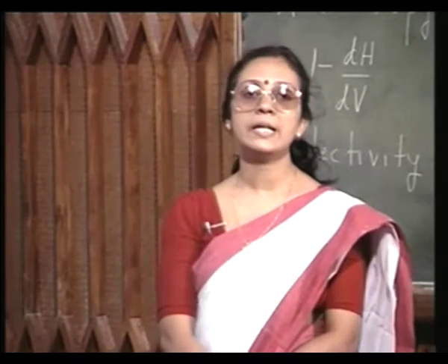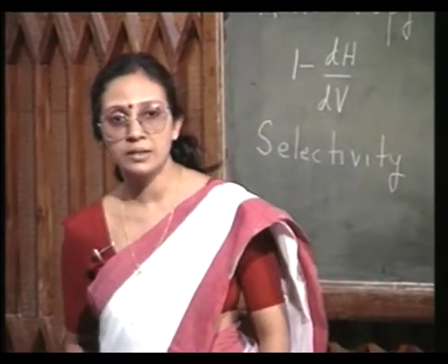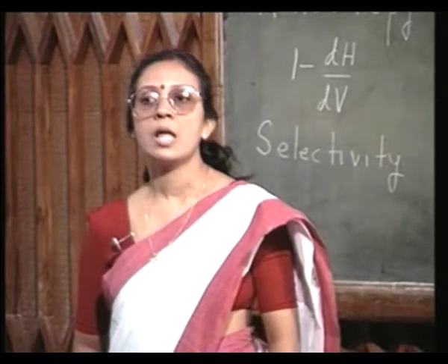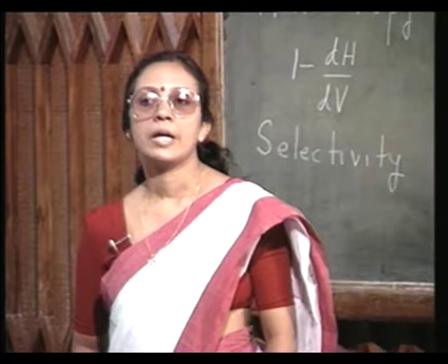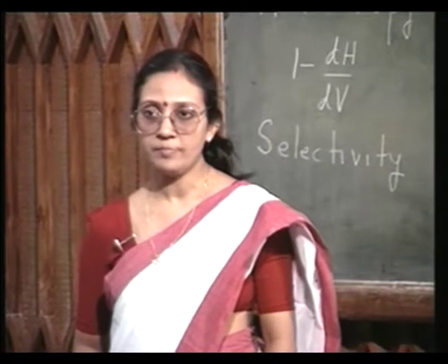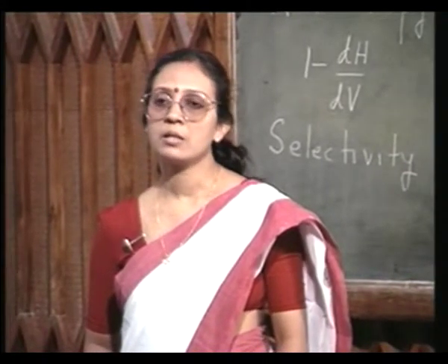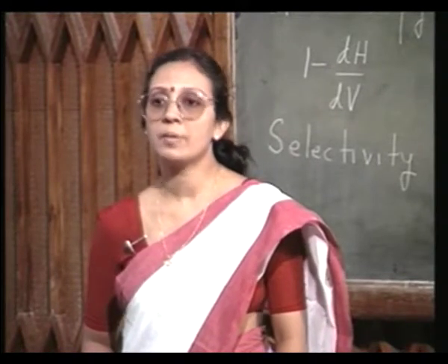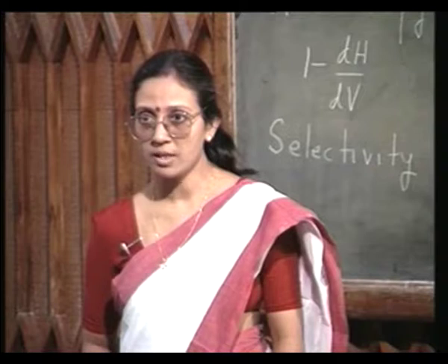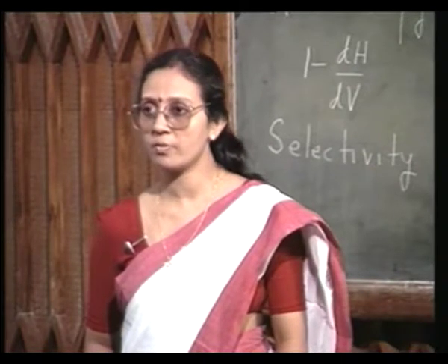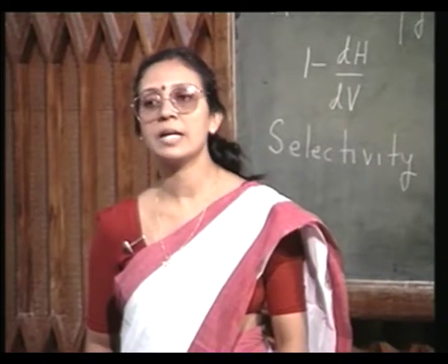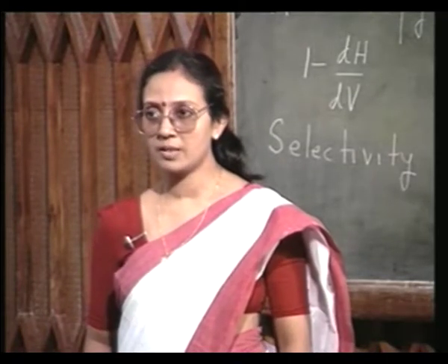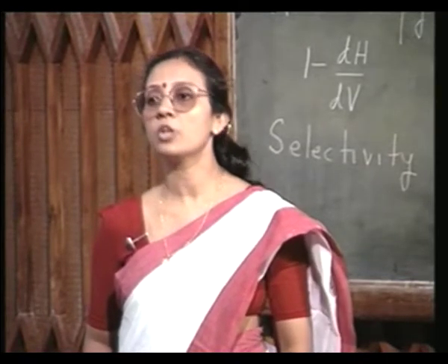So, for any etching system, these are the two figures of merit, anisotropy and selectivity, and any chemical etching system for that matter will have quite good selectivity, because some chemical reaction is taking place, right. So, material A is different from material B, therefore, material A will react with a particular etching material, but material B will not.